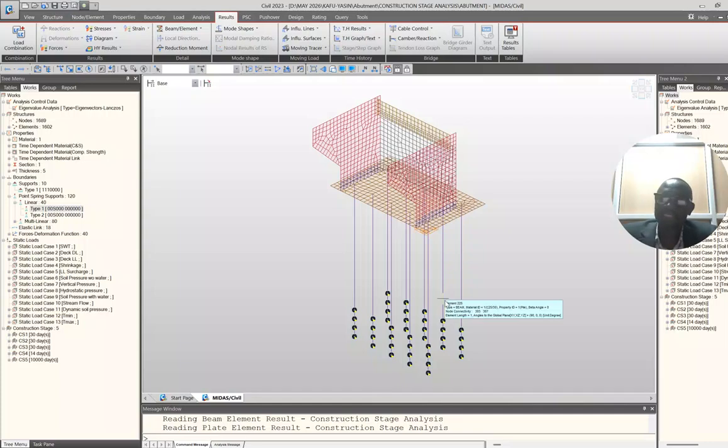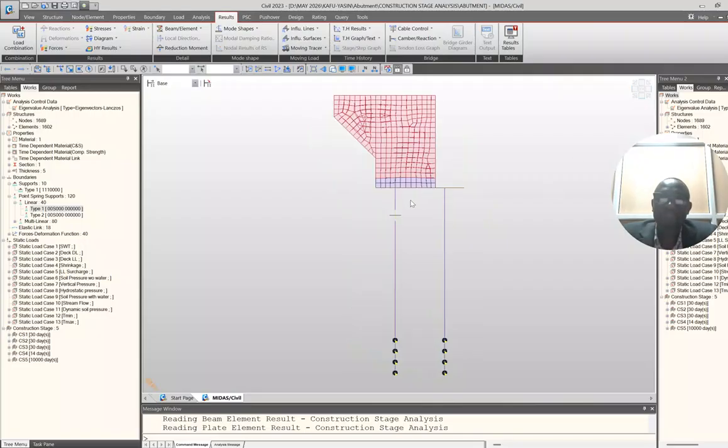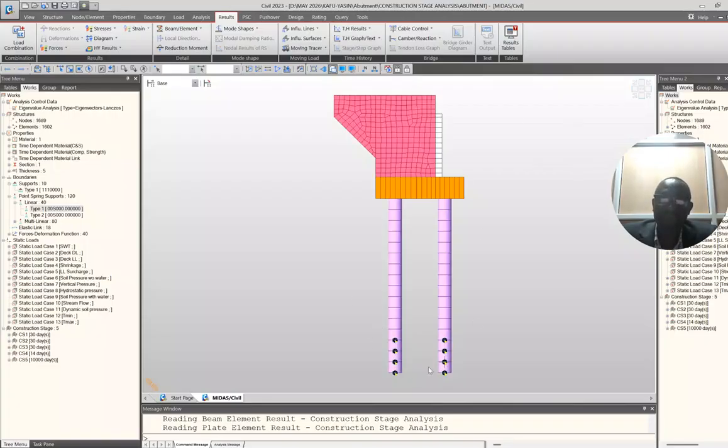This is, of course, at the construction stage. As soon as you are done with construction, you still have a scenario where this spring constant is up here. Then over time, scouring begins to happen. 10 years, 15 years, rapid flow, scouring will continue until the top of the rock, below which you now have to do the embedment. So if you do the design using Tomlinson and other models, basically you should be able to get the skin friction of the rock and other things so that the stability is held down here.